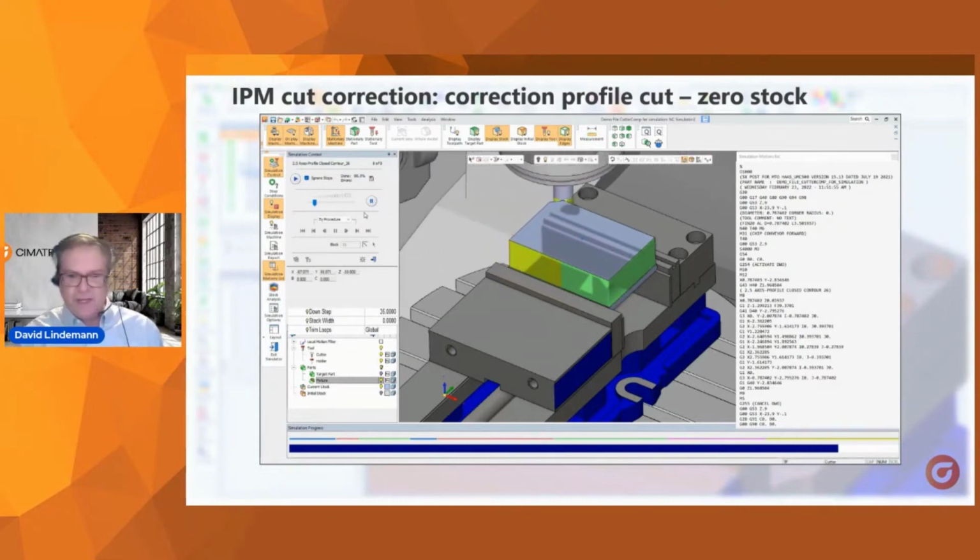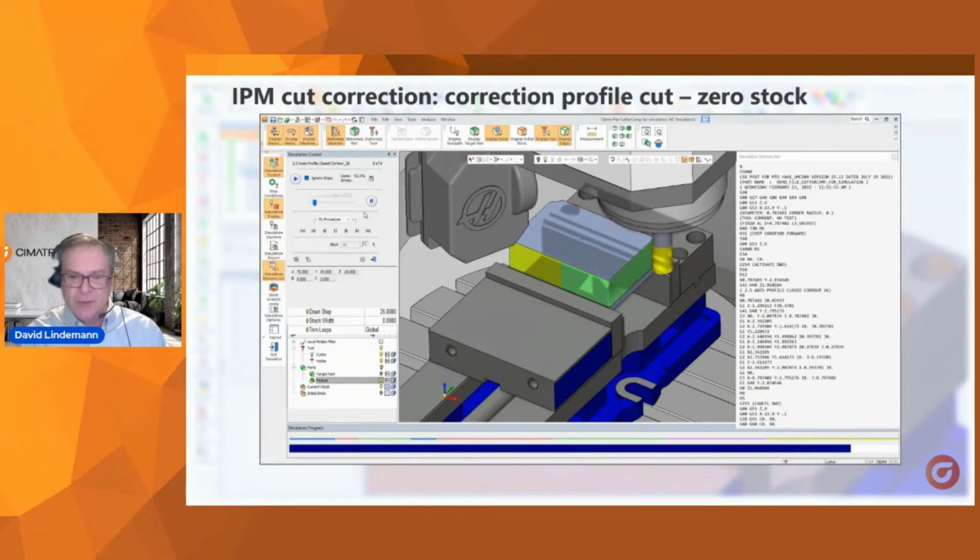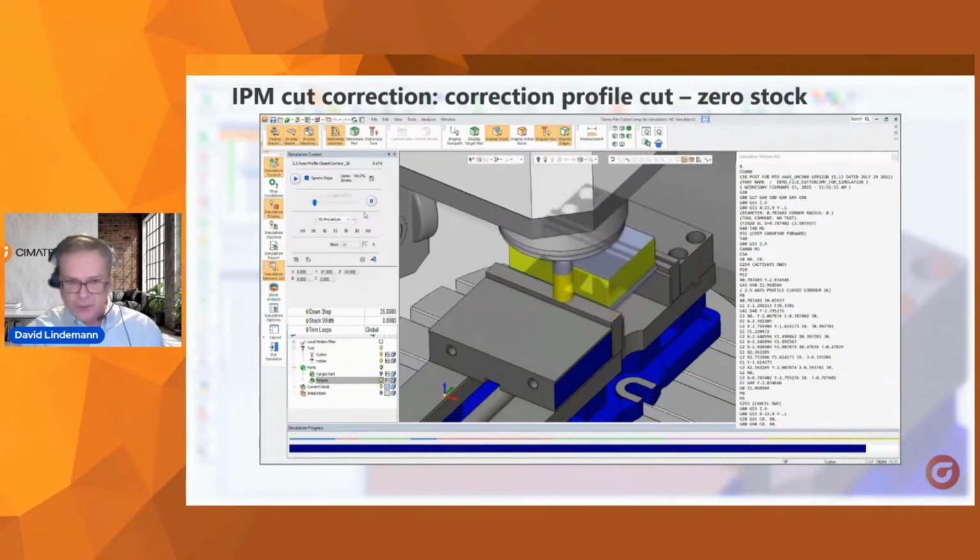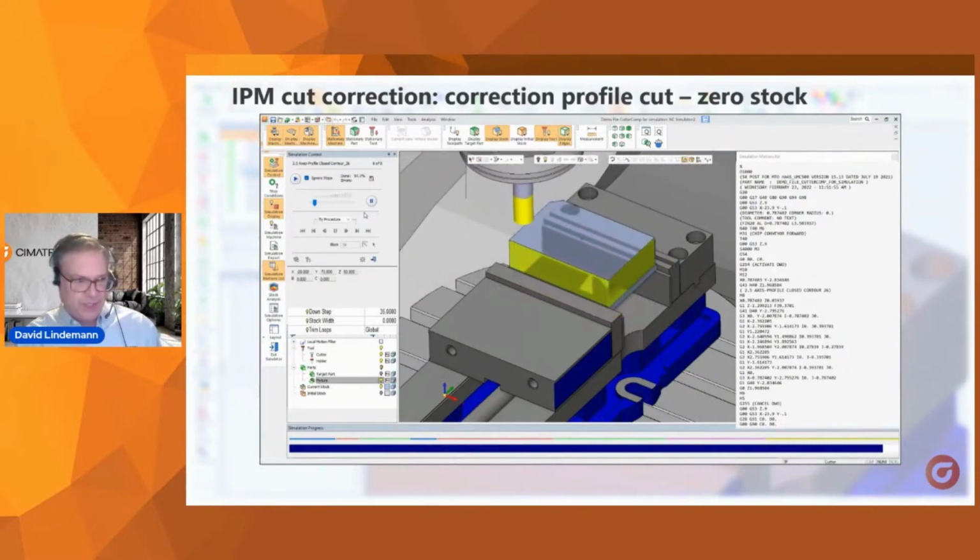So deflection, tool wear, we may not understand what those things are. We know we're going to recut it, so let's leave enough material so that we get a good recut. That's why we'll leave the 5/1000ths. We'll take that in addition to whatever deflection may have occurred. So again, the proof is on the machine. Let's go to the machine.